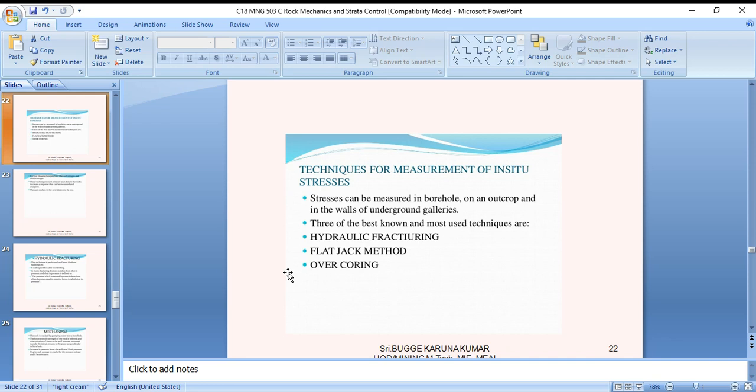Flat jack is a thin walled container designed to withstand hydraulic pressure of several thousands of pounds, which when properly confined by cementing or grouting in a borehole or slot in rock, these cells are used for a variety of purposes in rock mechanics investigation, including the measurement of forces, joints for load, a mine pillar, for applying force to instrument, the pressure transmitters and the pressure sensors.